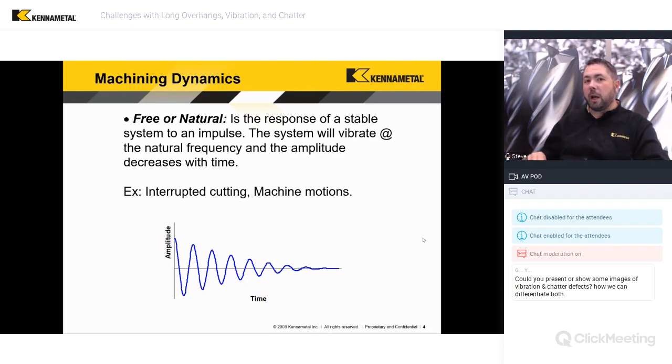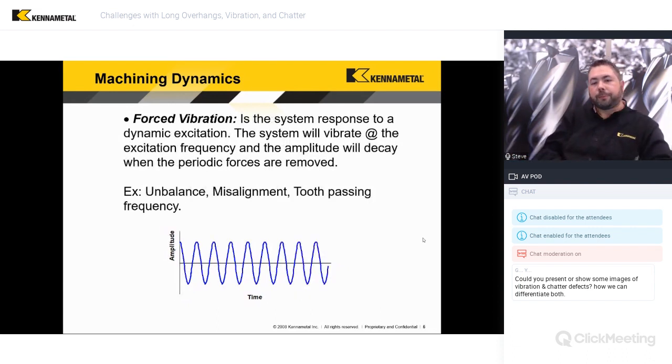It's very, very common. Most of us have heard parts of the machine, for instance, way covers, oftentimes, because they're thin, they're light, they're not very stiff. It's very easy to excite them. We hear it, okay, and then it damps out. However, the whole machine itself, and individual parts, so spindles, boring bars that we'll talk about later, all those types of things can also, from a rapid motion, end up with free vibration.